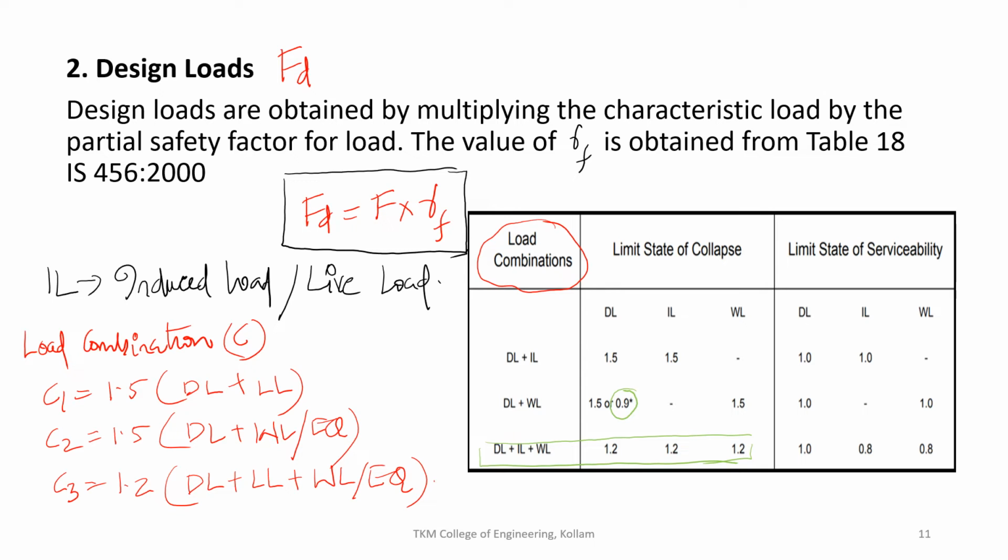And in the case of limit state of serviceability, what I have said for the limit state of collapse, that is limit state of tension, flexure, compression, is where we consider the load combinations in this way. But when you are considering the limit state of serviceability, that is deflection, cracking, etc., we will consider the partial safety factor as 1 itself. That is, we will not apply the partial safety factors for loads when dealing with the limit state of serviceability.